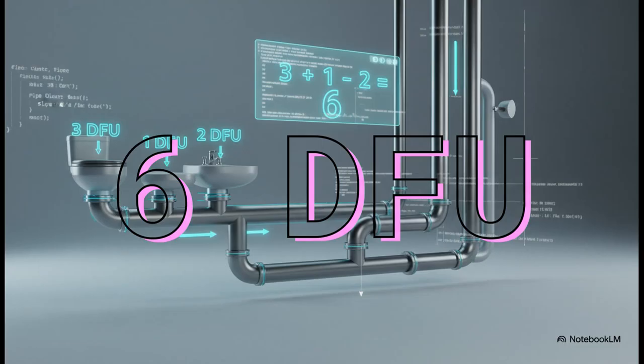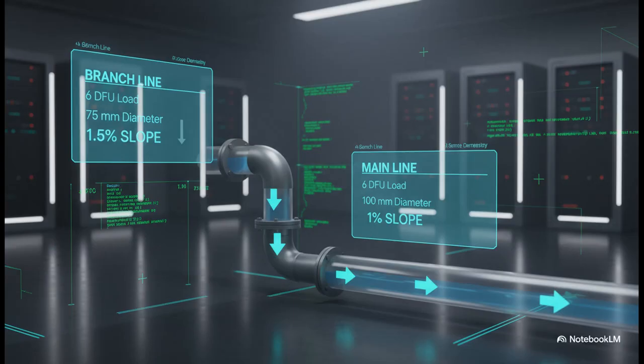So, let's do the math. We've got 3 plus 1 plus 2, and that gives us a total design load for this whole bathroom branch of 6 DFUs. Simple as that. So what do we do with that number? We take that 6 DFU value right back to our codebook, and it tells us that a load of 6 DFUs needs a branch line pipe that's 75 millimeters in diameter, and it has to be installed at a 1.5% slope. This branch then connects into a bigger 100 millimeter main line, which, you might remember, only needs that 1% slope. See? It all just fits together perfectly.